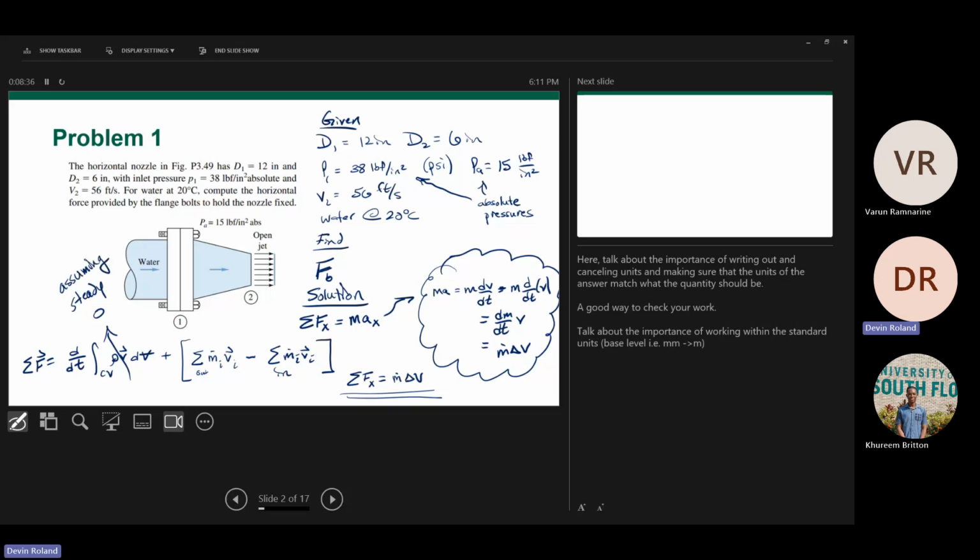If this was a transient problem, it would be a little bit different. Like if we were looking at a water hose and you turn on the water and you want to know the evolution of the water as it's approaching a steady flow rate, that would be where d/dt is not 0. But if you turn on the water and leave it alone, and the water comes out and it's just flowing, not changing, this is that scenario. Okay, thank you. Yeah, no problem.